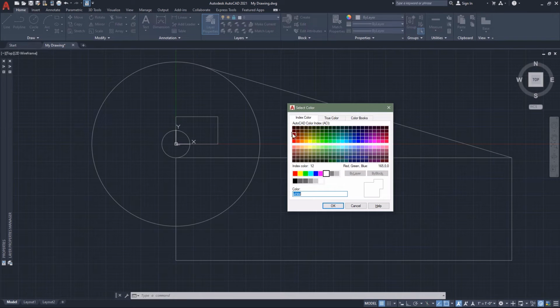In the upper palette, the colors are bold and even numbered, and the colors in the lower palette are pastel and odd numbered, and the color numbers increase in index value from left to right. An important note: at the midpoint on the right-hand side of the palette, the true color red, green, blue values are displayed for each index color.